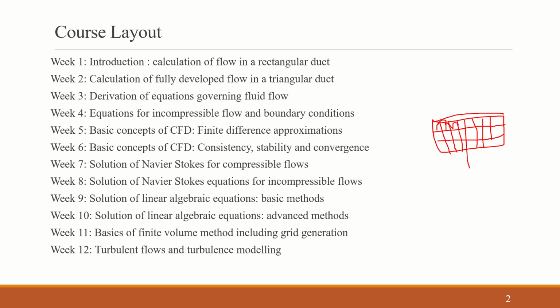So first, we need to know what system we are dealing with. Whenever we are approaching any CFD problem, we need to know what system we are dealing with, and that particular geometry we need, and for that geometry we use meshing, and we divide it into smaller segments. So for example, initialization: we need to know the geometry and we are meshing that geometry. These things we do in pre-processing, and after meshing we are giving the initial condition and boundary condition.